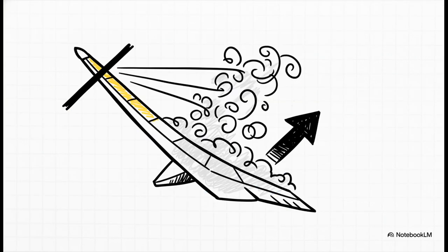But listen, all of these incredibly precise shapes have a breaking point. This is the absolute climax of that tug of war we talked about earlier. As the angle of attack, which is just the angle the wing meets the air, increases, your lift increases. But if that angle gets too steep, the smooth airflow abruptly and violently separates from the wing. When that happens, lift is completely destroyed. This is a very dangerous condition called a stall, and it's literally exactly what pilots spend hours training to prevent.